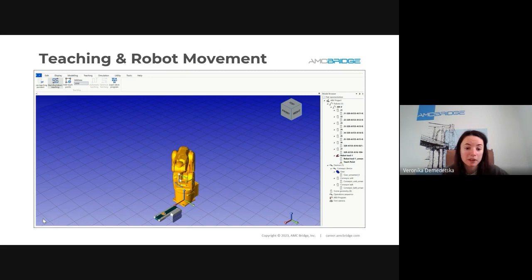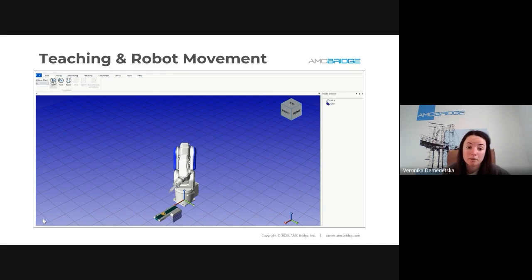For example, we can put the robot in the desired position that we want it to come to, and say, okay, that's the right position. I want to save this position under a specific address. For example, that's going to be 2000. And then during the simulation stage, we can ask the robot, okay, please go to position 2000. And likely it's going to go to that position.